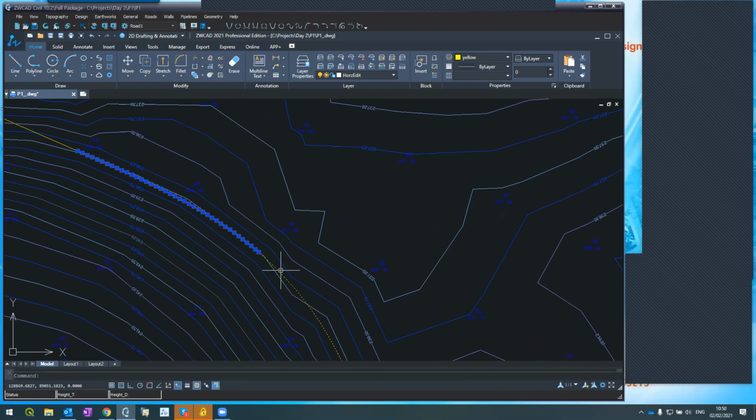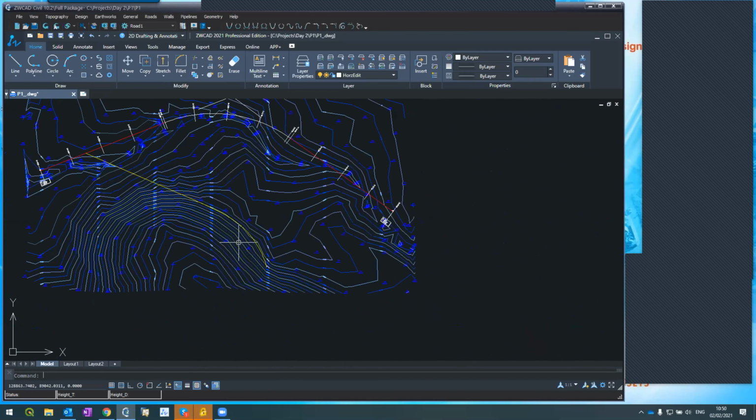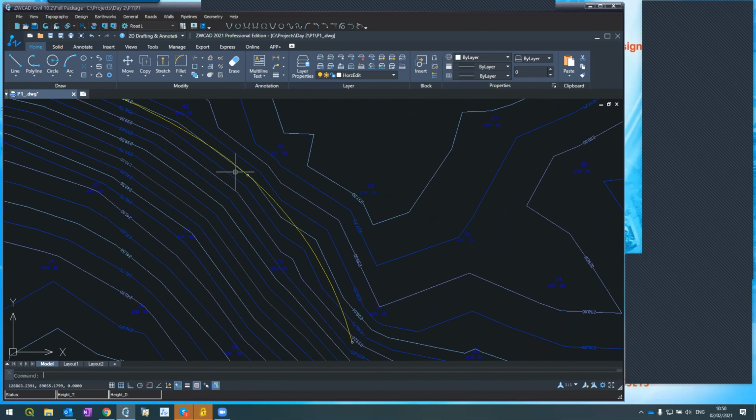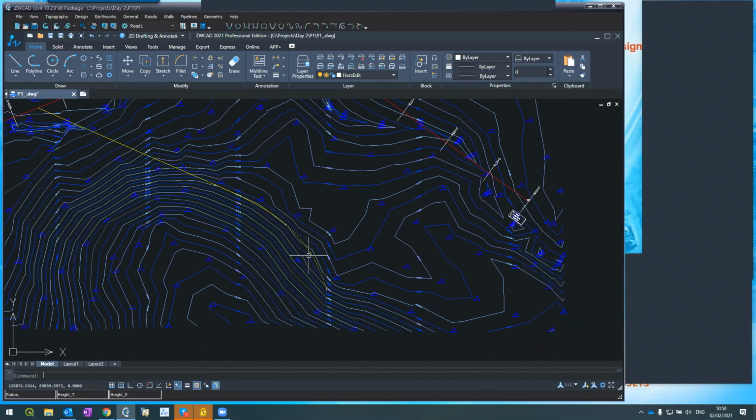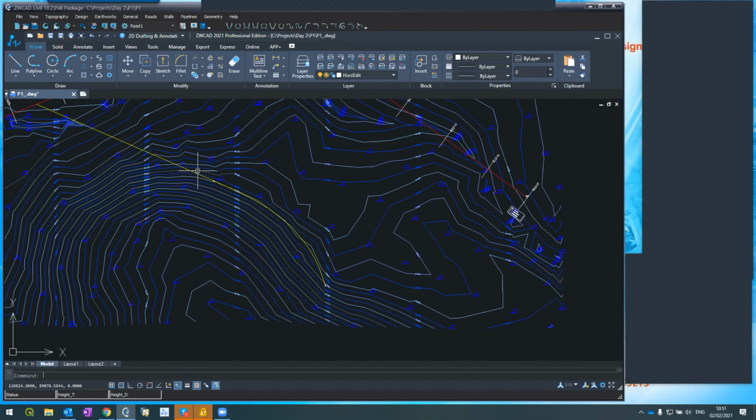By the way, it took the arc and shortened it a little bit so it would exactly fit the clothoid. So what I told the system is, connect the line with the arc and automatically calculate the transition between them. This is the geometry that I want, going along these contour lines. I hope you follow it. You will practice this in a minute. Let me finish.